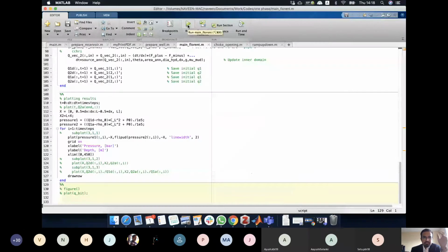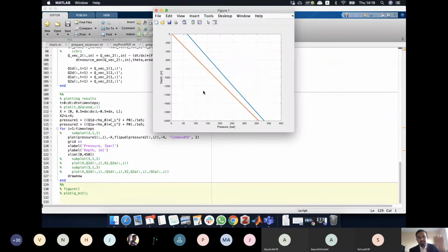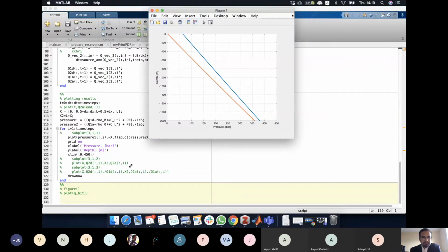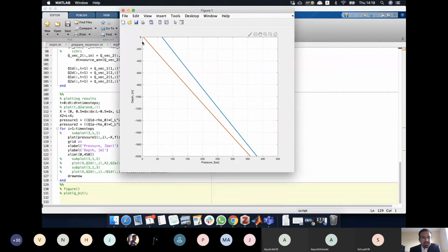You can see how the pressure increase from the choke travels down the annulus and also goes up the drill string and then keeps reflecting. So watch out. The red line denotes the pressure profile in the annulus, and blue is on the drill string. You have a pressure drop at the drill bit, and here is the pump pressure.